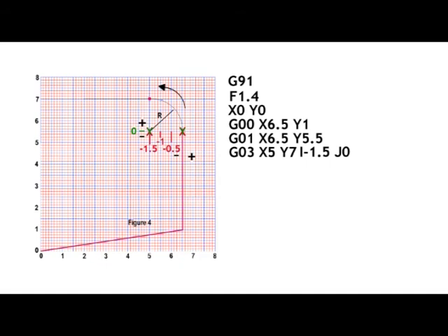Now you can add other required lines and codes for the cuts. G00 is for rapid transit, G01 for a specified feed speed based on the material and the RPM. For steel, the feed can be F1.4 for 1.4 inches per minute feed speed. For figure 4, we will start at X0, Y0. The line set will be, not including all of the lines,